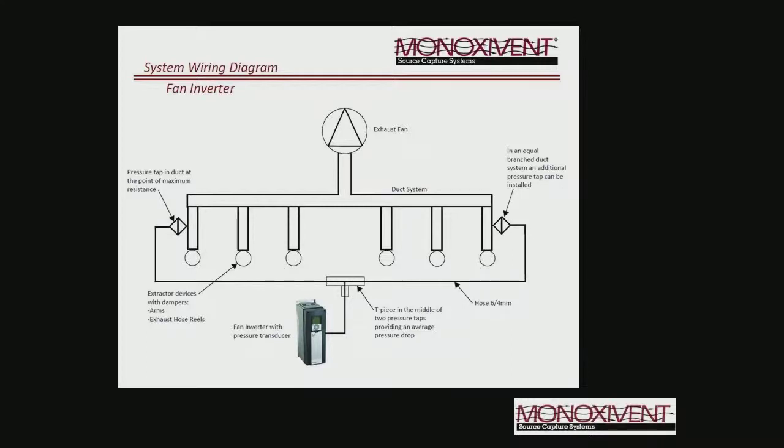As the dampers go closed, obviously the static pressure is going to go up, which is going to tell the variable frequency drive, hey, I need to slow down to get my static pressure back to 5 inches. So as the static pressure changes in the system, the VFD is always going to hunt for whatever specific static pressure we set the static pressure sensor up for.